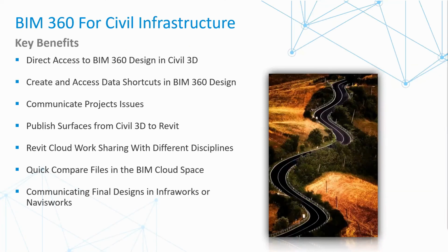So this is very critical when it comes to civil design and the guys working on site. We need to communicate, and BIM360 Design allows us to do that inside of BIM360, where the issue can be resolved and proper decisions can be made. The same goes for publishing the surface from Civil 3D to Revit. Yes, we can actually do this now in the BIM360 Design platform. So I can go and publish surfaces from Civil 3D to Revit, so the Revit users can use them. Then we've got our Revit cloud work sharing with different disciplines. So this is very critical. It ties back into the publishing of the surfaces.